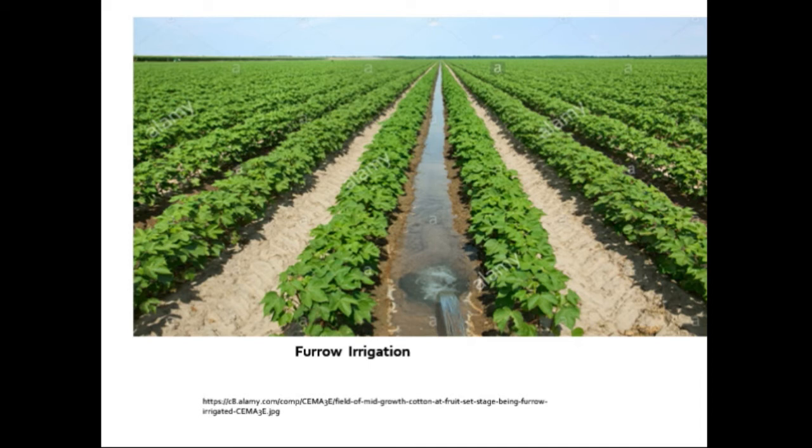Likewise, there are a few disadvantages of the furrow irrigation method as well. Some of them are: it is not recommended for very light soil having high infiltration capacity. Similarly, this may interfere with tillage, and it is usually expensive from the consideration of time and labor cost. There may be a serious erosion hazard, and adequate drainage needs to be provided, so that it may sometimes be costlier as well.